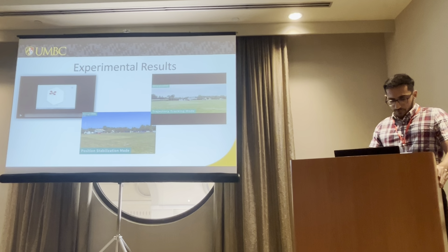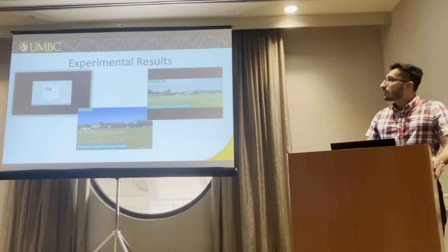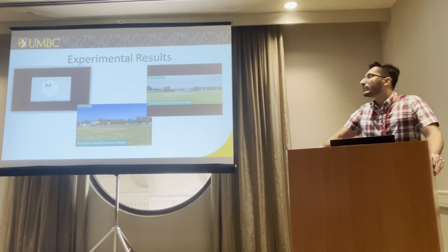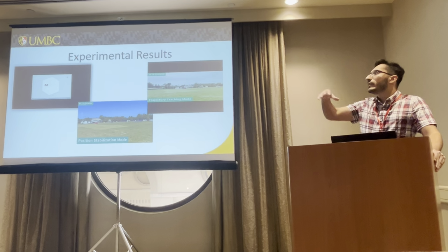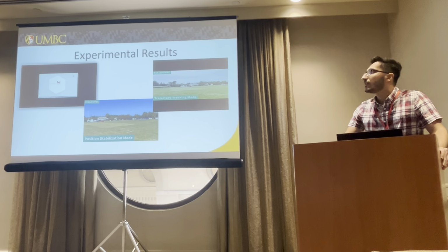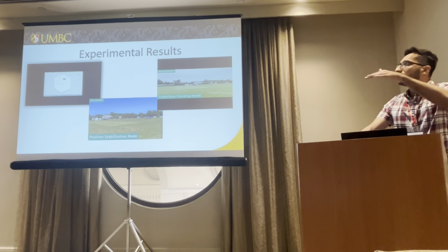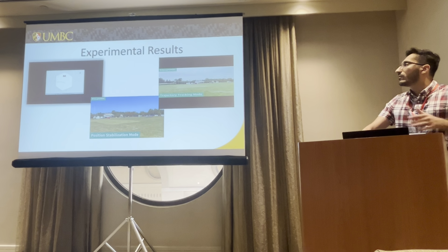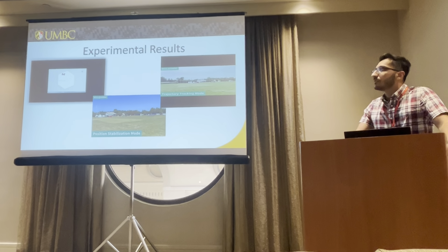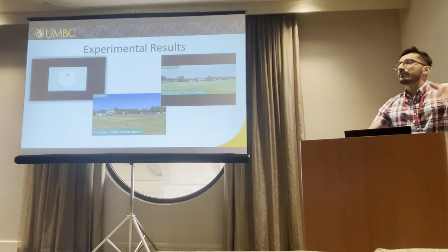Here I'm showing you some videos. The first video shows the learning process. As you can see at the beginning, the quadrotor is a bit jittery, moving around, not really able to follow the trajectory, but after some time it learns how to stabilize its attitude, and is also able to follow the helical trajectory. All the gains are initialized at 0, there's no prior stabilization controller, and the learning happens as the quadrotor moves.